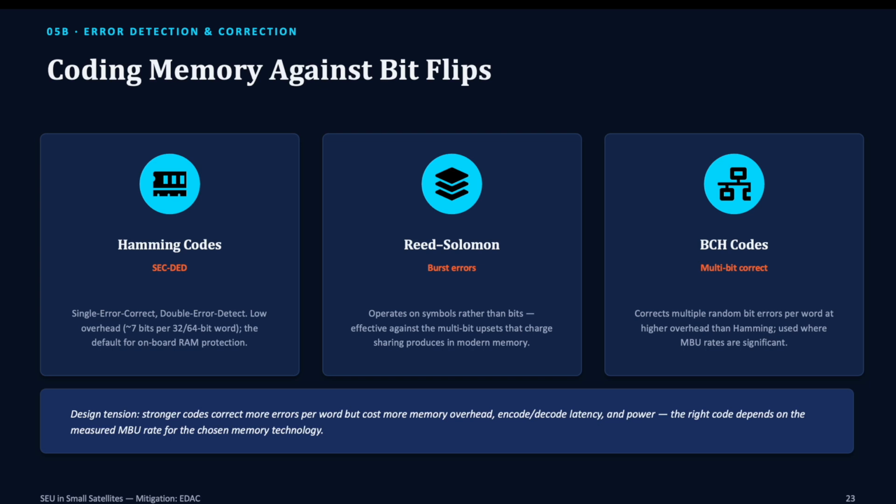The Hamming code is more of a default. The Reed-Solomon and the BCH matter more as multi-bit upsets become more common in smaller nodes. The overhead versus correction strength trade-off is a real design decision that people have to make when designing these architectures.